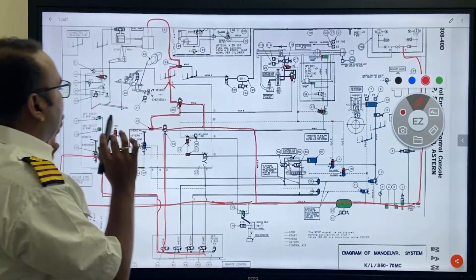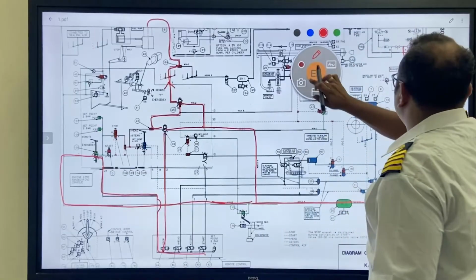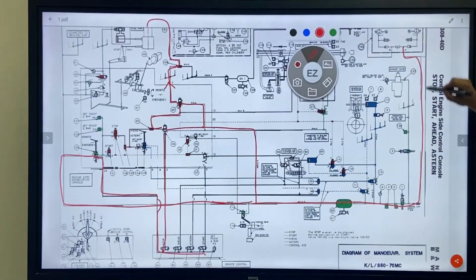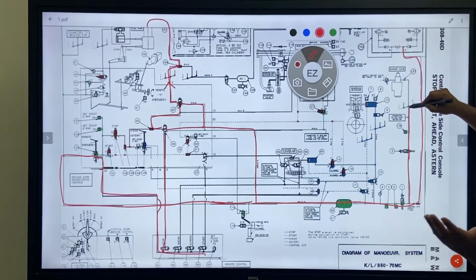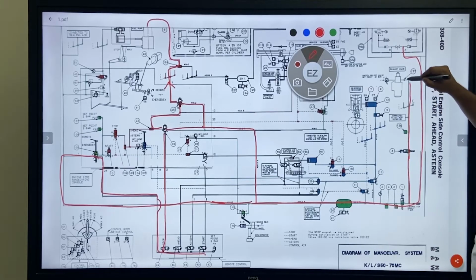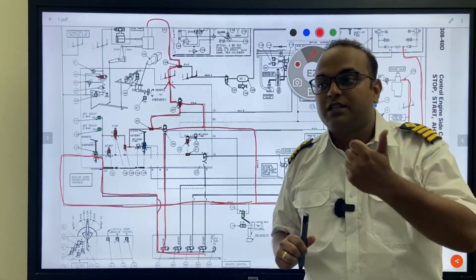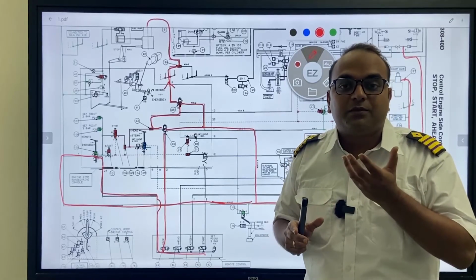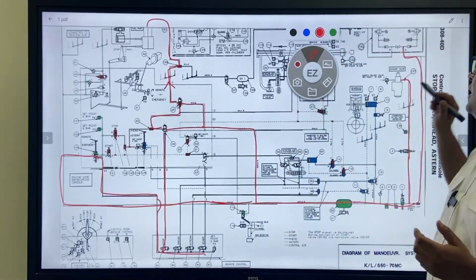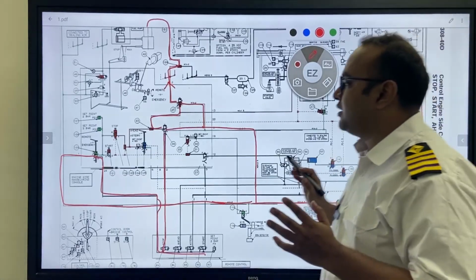So I hope till this point it is quite clear with you what is going on. At the same time, from this control layer, one line went up via this direction control valve, and through various units, like there are 6 units, we are showing one. It went to the exhaust valve, the same exhaust valve which we have discussed in the exhaust valve system. What air does is it goes and pressurizes the air piston and keeps the exhaust valve locked in the closed condition.